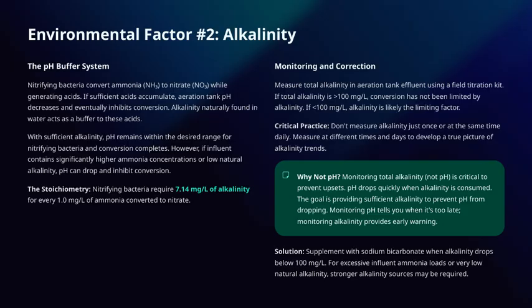Here's a critical point. Don't just measure alkalinity once a day at the same time. You need to measure it at different times and on different days to get an accurate picture of the trends. Why is this important? Because monitoring pH alone isn't enough.